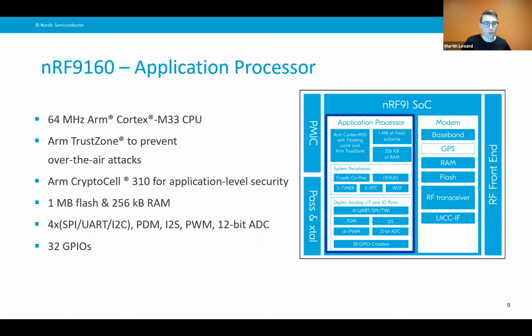We also have support for the typical peripherals, SPI, UARTs, I2C, PDM, I2S, PWM, 12-bit ADC as well. And you also have 32 general purpose input outputs, that you can program and connect whatever sensors or other devices you want. So that's the application area.